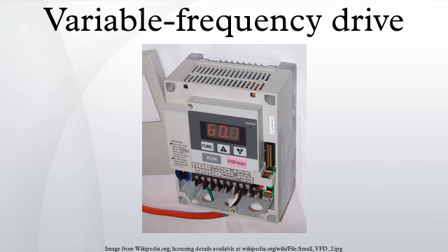Variable speed drives can also run a motor in specialized patterns to further minimize mechanical and electrical stress. For example, an S-curve pattern can be applied to a conveyor application for smoother deceleration and acceleration control, which reduces the backlash that can occur when a conveyor is accelerating or decelerating. Performance factors tending to favor use of DC over AC drives include such requirements as continuous operation at low speed, 4-quadrant operation with regeneration, frequent acceleration and deceleration routines, and need for motor to be protected for hazardous area.